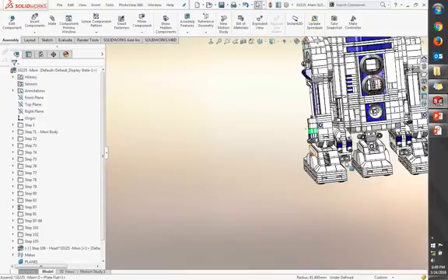But if you're running any kind of animations, SOLIDWORKS will move a little bit, rebuild, move a little bit, rebuild. So you can actually animate this and see a movie of it flexing in space. So you can see the part comes here. Now, these are virtual components. The reason is I don't want a part file on the outside that's wiggling around all the time. That's just something we run into.